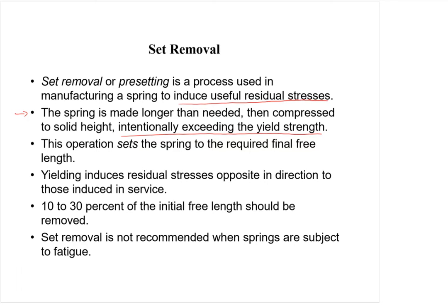So this way the spring is more stable. In case you do overload the spring, it's not going to suddenly change its dimensions on you. It's already been preset. It's already had the yield removed at the solid length. And now if you reach the solid length again, the spring doesn't care.